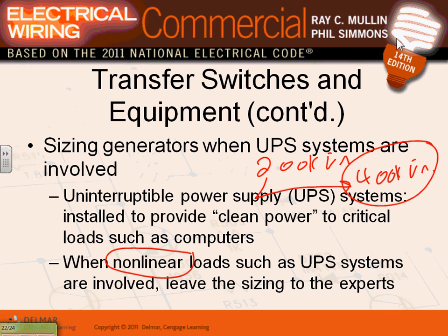Harmonic loads are very bad for generators. With the software that we have, guys, your software will take this into consideration. When you have VFDs or UPS, it will double the load to allow the generator to pick up the ugly, dirty load that the UPS and VFD are going to create in your system. So keep in mind, I don't worry too much about these because we have the software, guys.